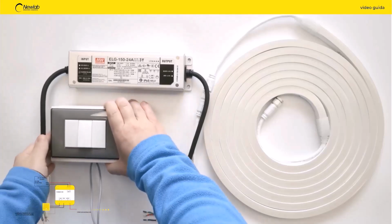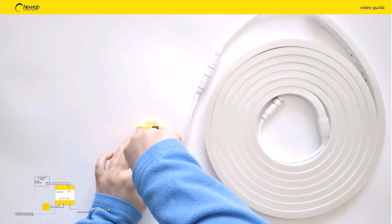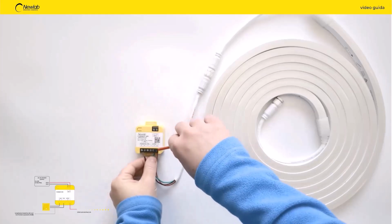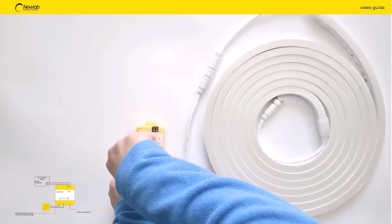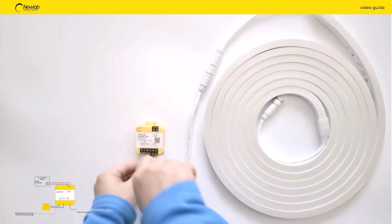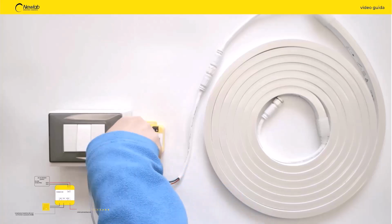a normally open push button. Connect the positive pole of the strip to the output plus terminal of the dimmer. Connect the data input of the strip to output D terminal. Connect the negative pole of the strip to the output minus terminal of the dimmer. Connect a normally open push button between the push P and COM- terminal.